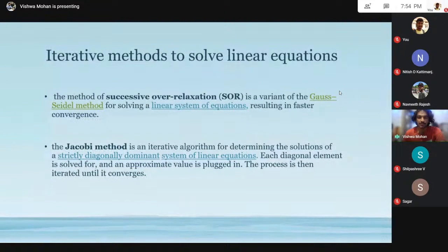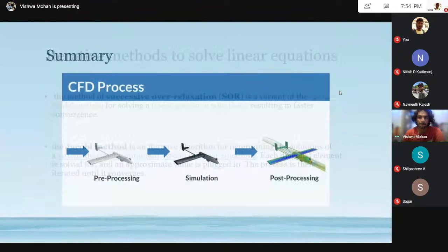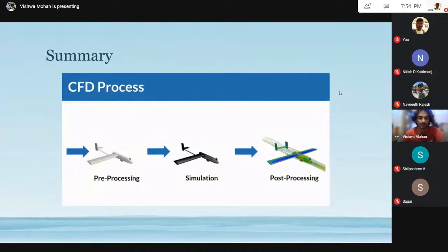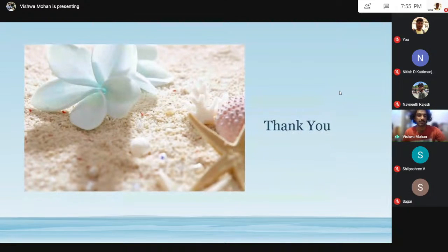And these are certain methods that we can use. So basically this is the summary. Pre-processing, which involves boundary setting, material setting and everything, and involves the meshing, which is creating discretized cells, and then simulation, and then post-processing. So now is the time. I hope most of you stuck around for this, but yeah, now it's time for the live simulation.